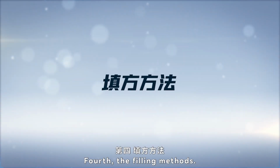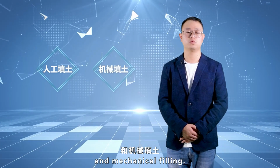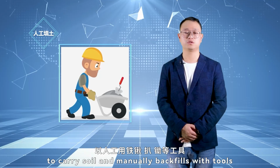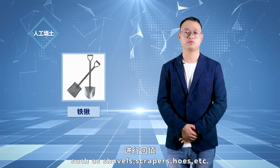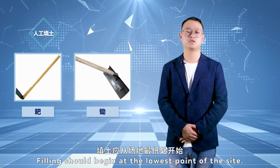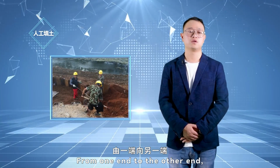Fourth, the filling methods. The filling methods include manual filling and mechanical filling. The manual filling method uses trolleys to carry soil and manually backfills with tools such as shovels, scrapers, hoes, etc. Filling should begin at the lowest point of the site, from one end to the other end.